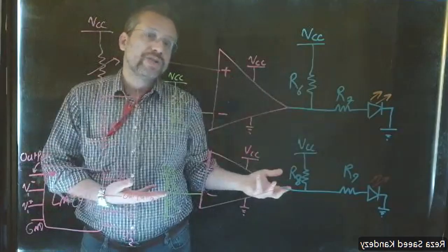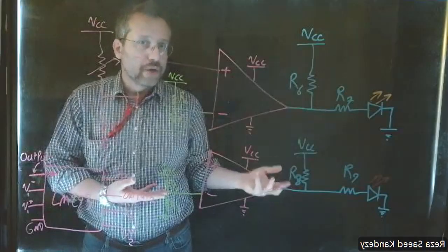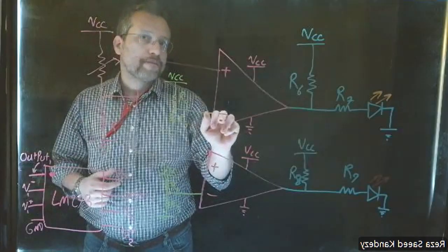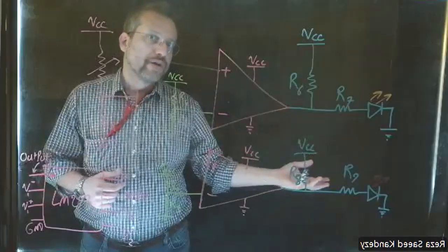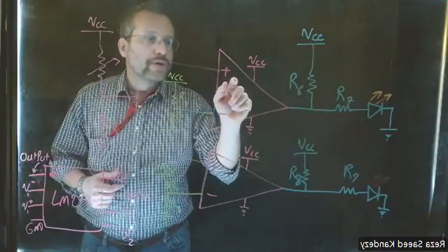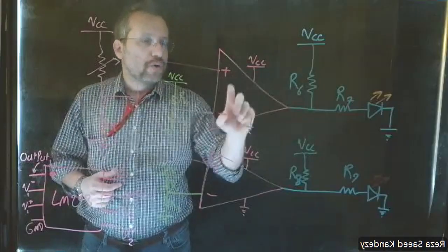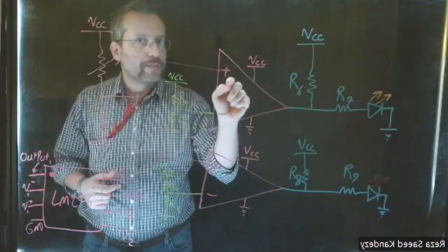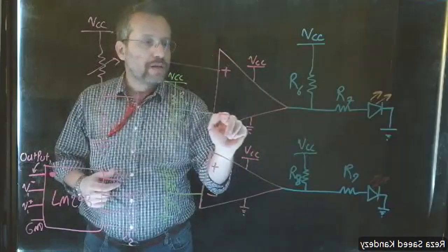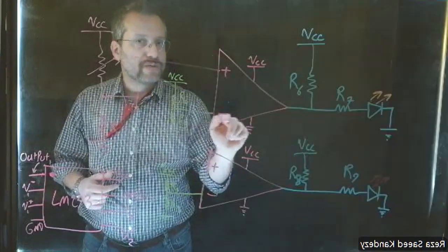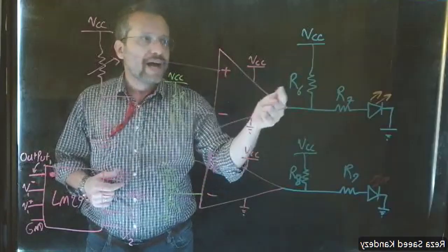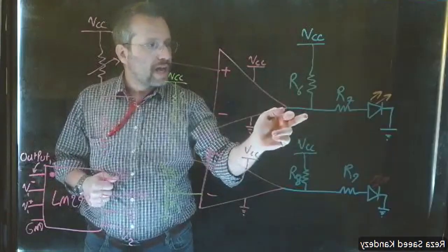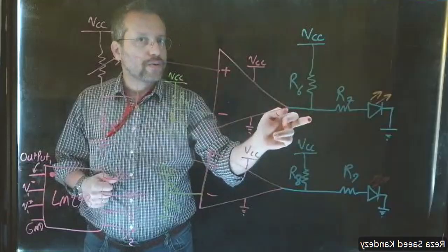We are going to use these characteristics of the op-amp and set the inverting terminal as a reference value, and then use our input in the non-inverting terminal. So if the non-inverting one is bigger than the inverting one, which is our reference value, then we have a high or positive voltage, which means a high value in our output.